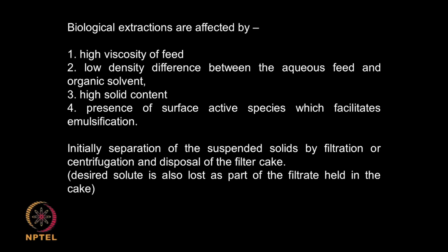It could be a metabolite, it could be a protein or enzyme and so on, but there are many issues here in biological systems because the feed will be highly viscous. The feed that is coming out of a fermenter broth is going to be very highly viscous, and there could be low difference in the density between the aqueous feed, that means the fermentation broth, and the solvent which you are using. That is another problem.